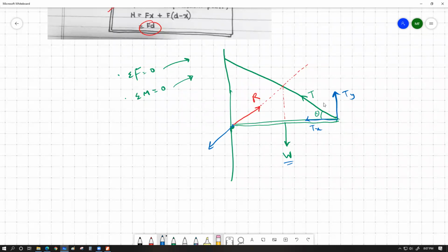That's why drawing it to the downward left direction is not the correct choice. Rather, drawing it on the upward right direction is the essential correct choice. The bottom line of this discussion is that if we have multiple forces working on an object where the object is defined to be in equilibrium, or if we want to derive the condition for the equilibrium, for resultant moment to be zero, all the forces must go through the same point.